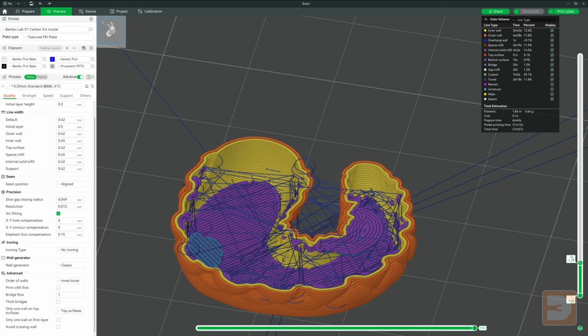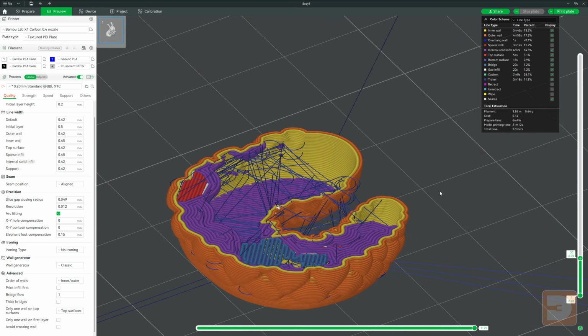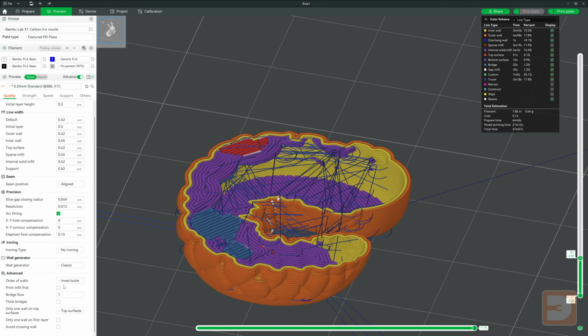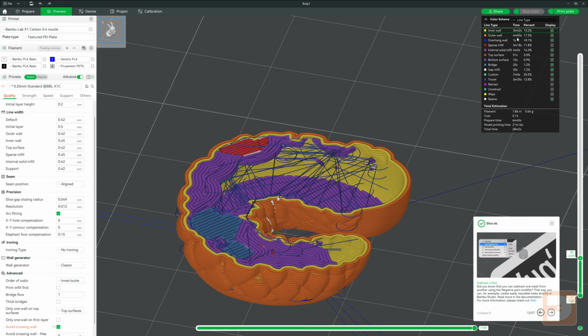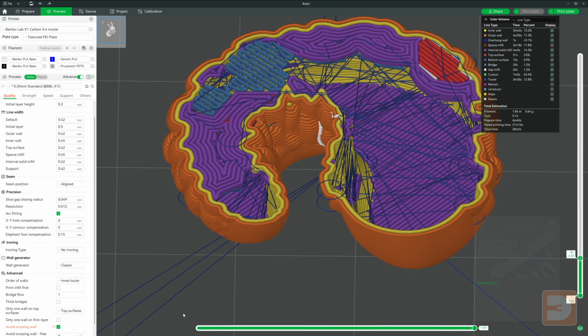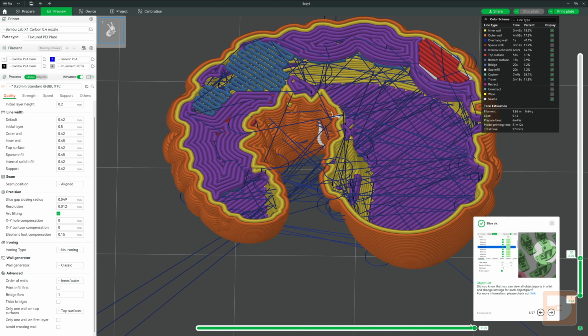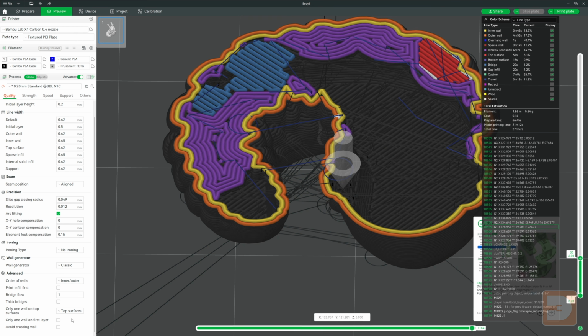This is the movement that the nozzle will be making in areas where it's not actively extruding. If retraction settings aren't spot on, or if your filament isn't playing ball, you can find that thin strands or strings can be accidentally printed when the nozzle follows these paths. With this feature turned on, it tries to avoid travel paths which involve crossing over exterior walls as much as possible, as if stringing occurs within the exterior walls, you're never going to see it once the print is finished. Whilst this can help with stringing and blobbing, it can also massively increase the print time, as the nozzle is then going to be following longer paths to get where it's going without crossing the wall where possible.